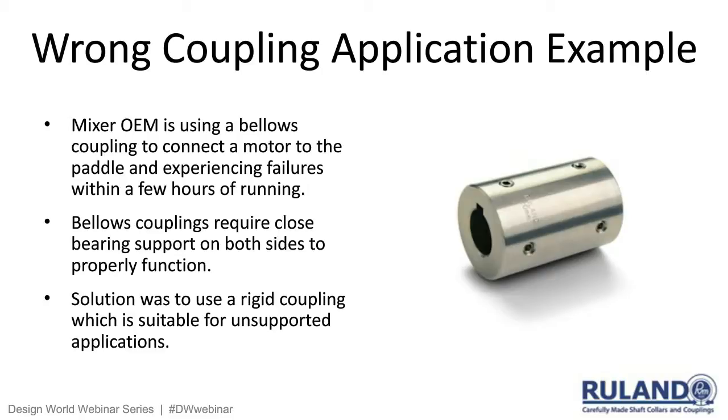The only coupling that has a possibility of working with bearing support on one side only is a rigid coupling. And again, even at that, you should review the application just to be sure.